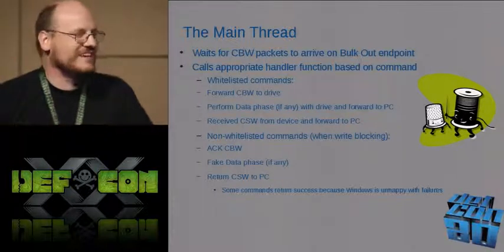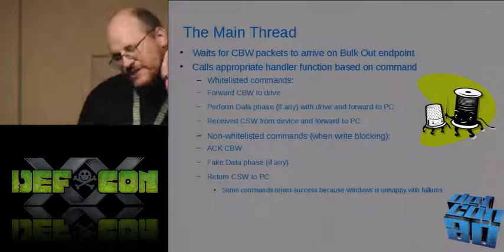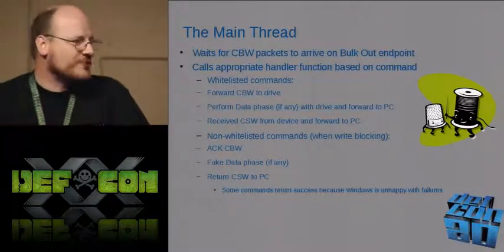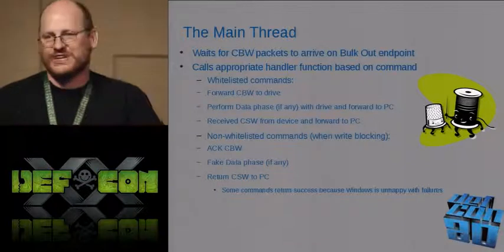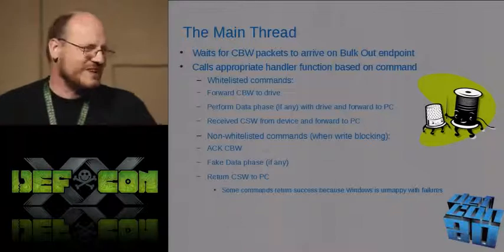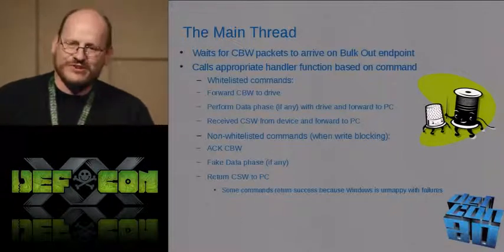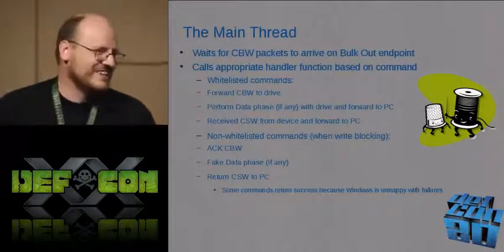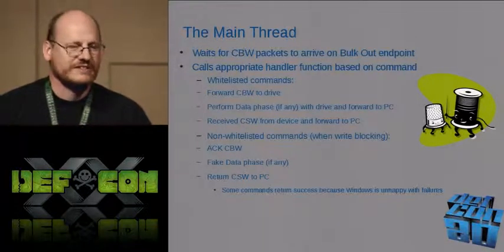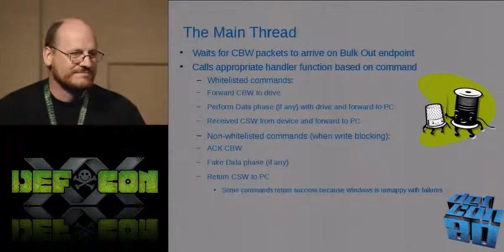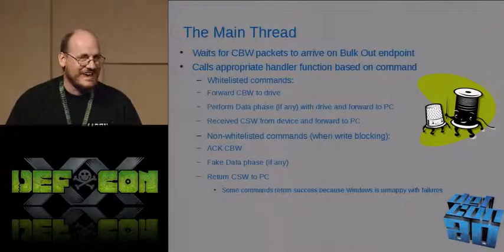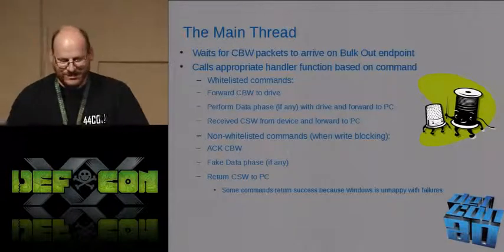It worked. All right. Now, initially, in an early design of this, I actually returned an unsupported command status if you try to do things like format my drive or write to it. And what I found is that, strangely enough, Windows does not handle it correctly. So you tell Windows, unsupported command. What do you think Windows does? Tries again, and again, and again, and it never gives up. It's really obnoxious.